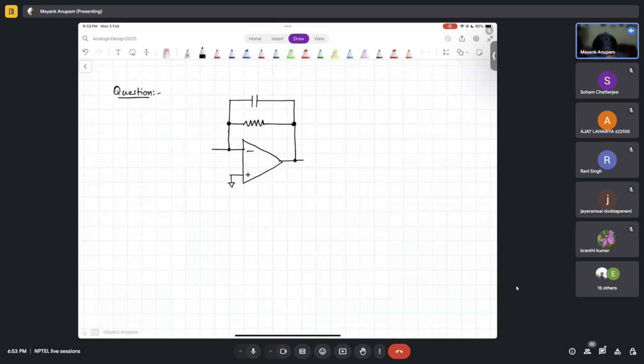Whenever you have more than two wires intersecting at a particular point, you have to give this junction dot. This is a convention in schematic drawing. Whenever you draw a schematic, make sure that you follow this. A junction is a point where three or more wires intersect, and you have to make sure that you put a junction dot here. This is a good practice.